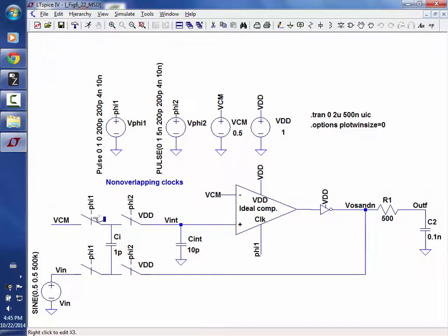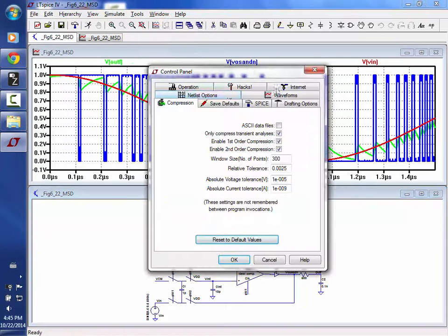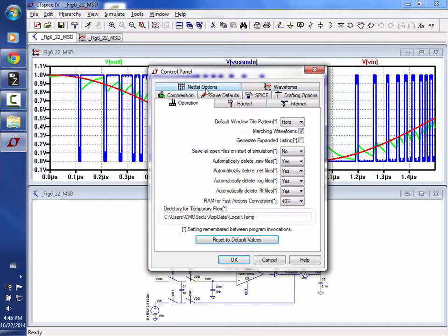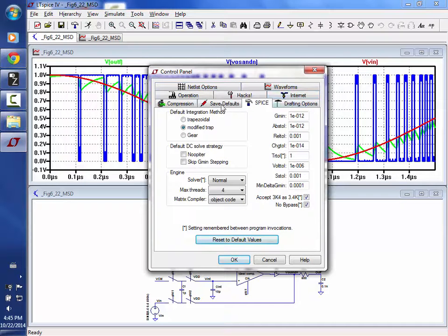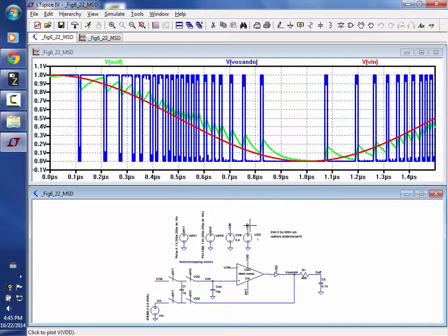So this is the switch capacitor. Basically what I just derived is this, and I didn't put in the quantization noise or phi. I don't want to spend the time doing that. So let's hit run, and then you can say, gee, it works. Let's also, for the heck of it, plot the current that's pulled. Where is that? In Spice, where's save device current, save default? You should be able to. Oh, there we go.